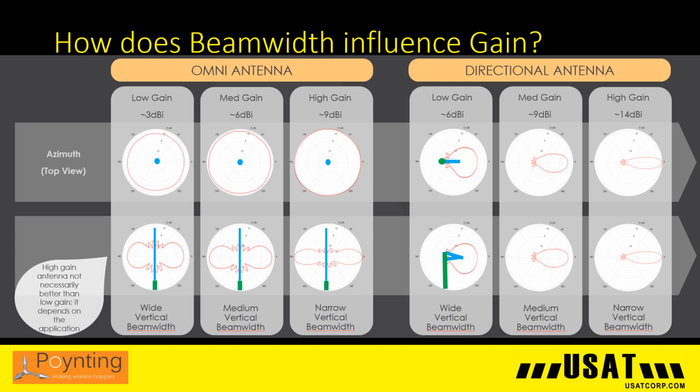There's a lot of math and fundamental equations as to how beam width and gain relate to each other. Looking at the Omni antenna on the left, what you want is that it radiates equally well in all directions. Looking at the top view, in general they all do. Here's 3 different Omni antennas with a top view of increasing gain patterns.